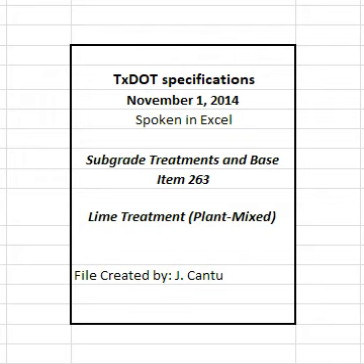3.1 Storage facility. Store hydrated lime in closed weatherproof containers. 3.2 Mixing plant. Provide a stationary pug mill that uniformly mixes lime, water, and base material in the specified proportions. Obtain approval before providing weigh batch or continuous mixers. Equip plants with automatic proportioning and metering devices. Ensure weighing and measuring equipment complies with Item 520, weighing and measuring equipment. Provide calibration documentation.